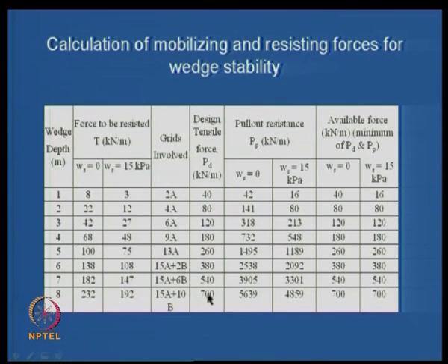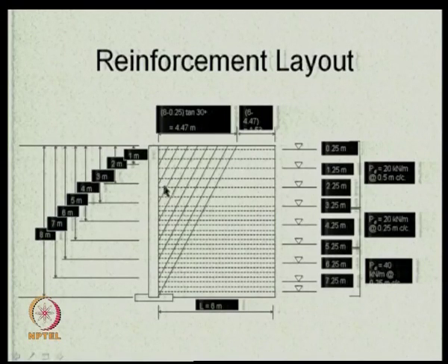So, essentially one needs to formulate a sort of evaluation like this, and in fact there are many software available to calculate. This is the way it should be provided, like 1 meter, 2 meters and all that, and the design spacing should be 0.25, it should start here, and then you can have spacing, and L is the length of reinforcement. So, one should be able to design a suitable reinforcement layout, and there are many software that are available. They are company specific. One can also design systematically using an Excel program.